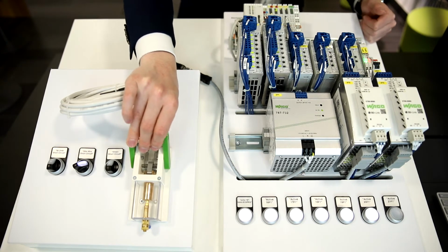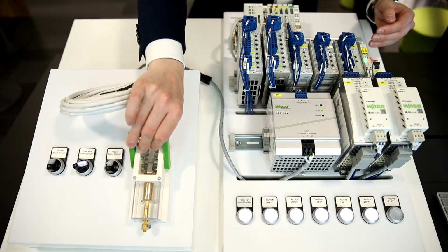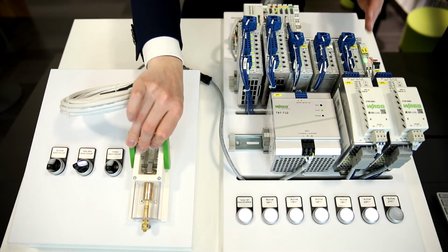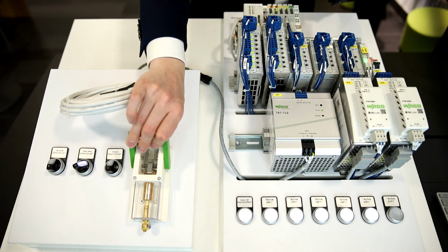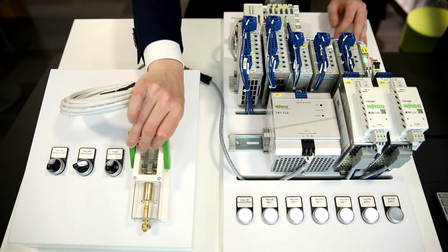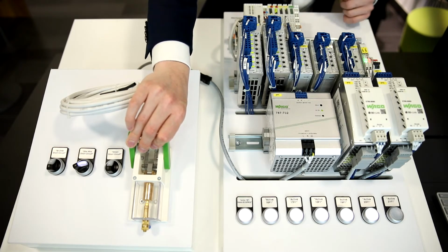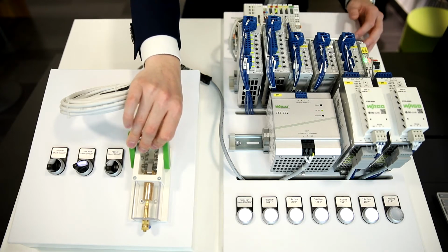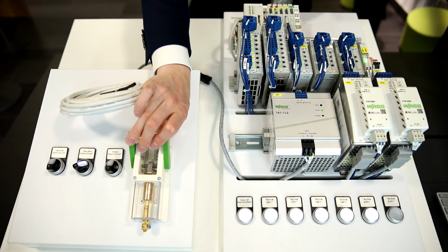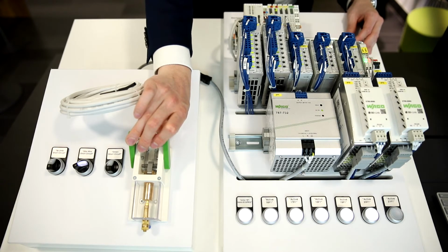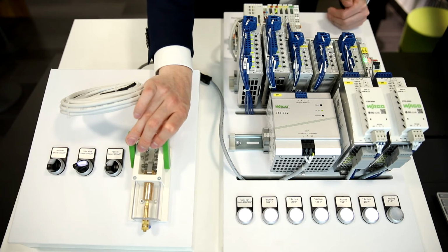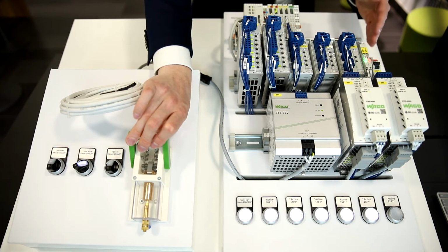It takes a long time for the triggering because we have a miniature circuit breaker with 2 amp and we have right now around 4.6 to 4.7 amp overcurrent. With the characteristic of this miniature circuit breaker we need roundabout 3 to 6 times overcurrent. This means 6 to 12 amp and we just have 4.6 amp, so it takes a long time for the triggering. Let's have a look at what happens in the next minute.